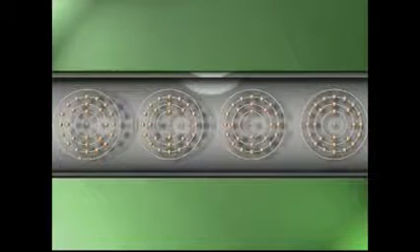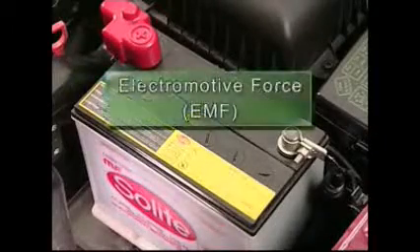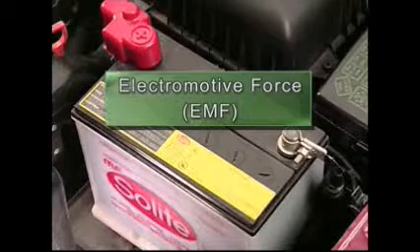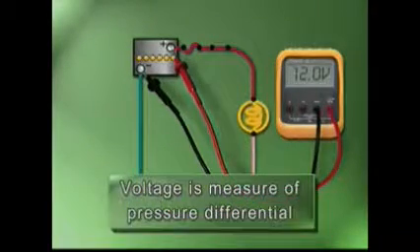In order for the electrons to flow, a pressure must push the electrons through the path that completes a circuit. The pressure in an automotive electrical system is called electromotive force, or EMF. Electromotive force, or voltage, is the measurement of the pressure at a point in the circuit where there is an excess of free electrons to a point in the circuit where there is a shortage of free electrons. In essence, the measurement of voltage is the measurement of the pressure differential or the potential to move free electrons through any point in a circuit.